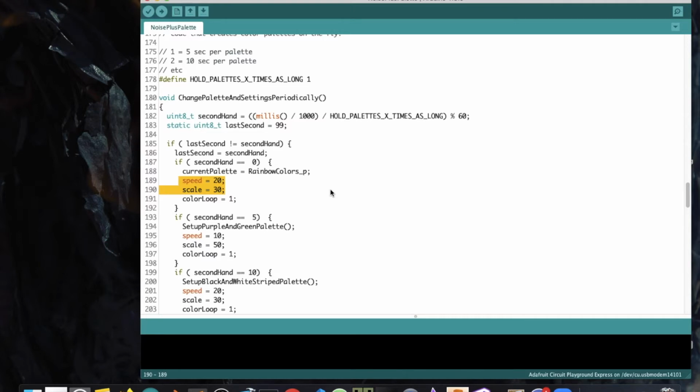And of course you don't need to limit yourself to driving colors and brightness with noise. It can be a great driver for pixel position, animation speeds, fades, or any animation parameter that runs from 0 to 255, which in FastLED is most of them. Use the map function for the rest.